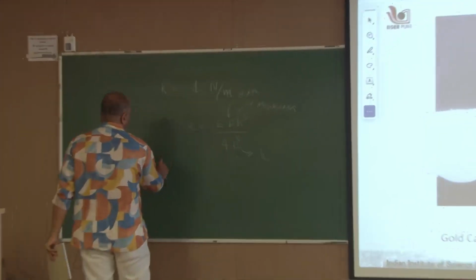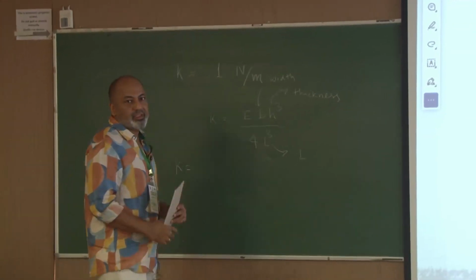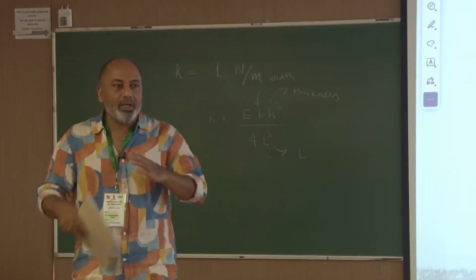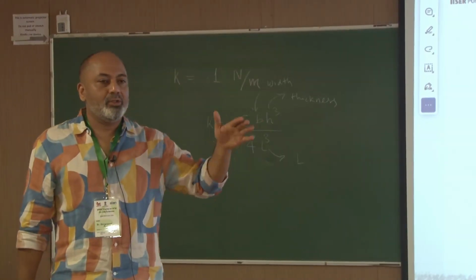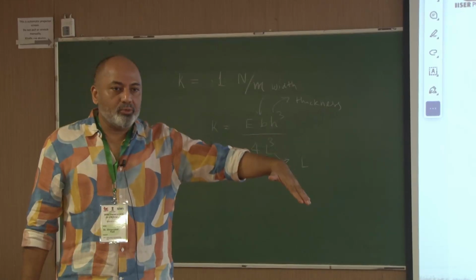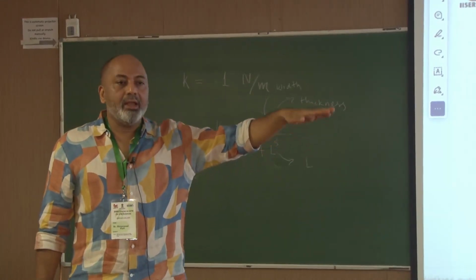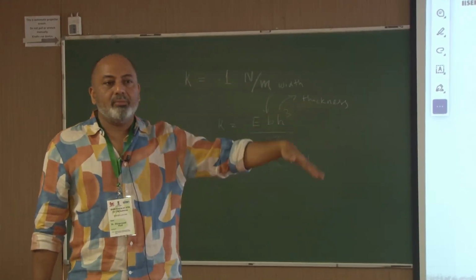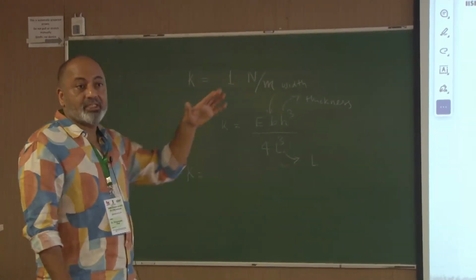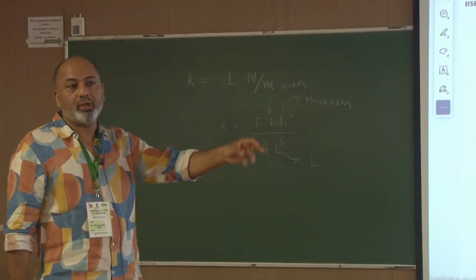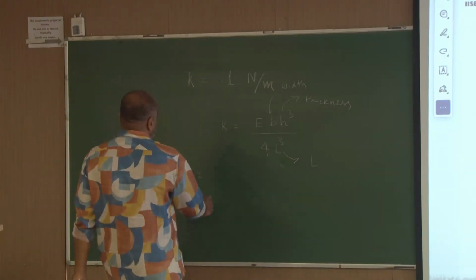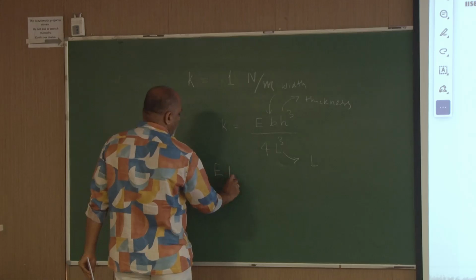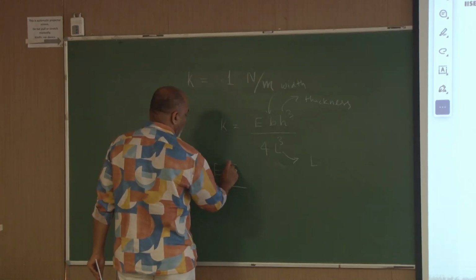Well, typically the stiffness of this is some bit of civil engineering or mechanical engineering. Cantilever beams are quite common in civil engineering. So if I have a beam, and I attach a weight at the end and it bends down, how much it bends down by, with what stiffness it will have for a given amount of weight, how much bending it will cause, this is done by a flexure equation. It's called flexure